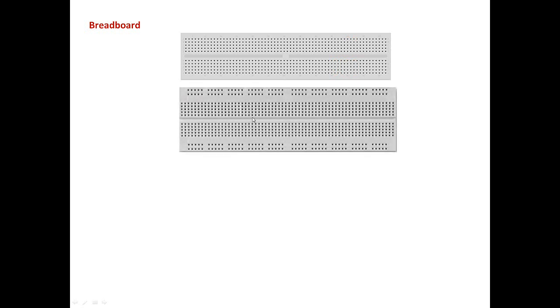They come in different shapes. This breadboard here has the top bank and the bottom bank, like we stated, but also it has power supply rails. This here, the horizontal rail, is a single node. They are basically used for power supply.